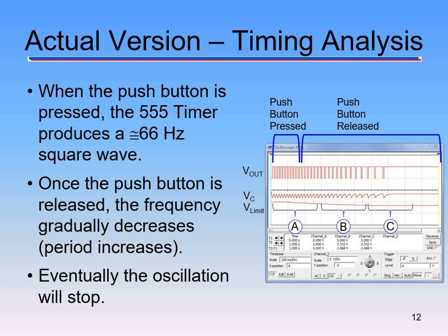It's just like when you're playing a fighting game and you hit the random button, so it chooses a random character for you. That's really all that that's doing. It's just toggling through all the different possible combinations as quickly as it can. And then once it doesn't get that voltage it needs anymore to change it, it'll stop when the last voltage is at high. So when V out's high, wherever we're at in the computing process of the combo logic, that's where we're going to get that digit output.